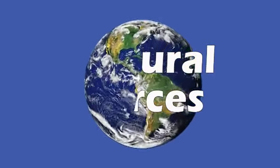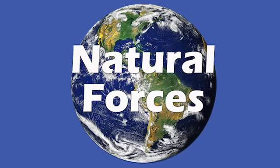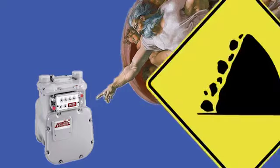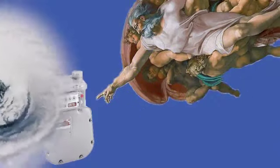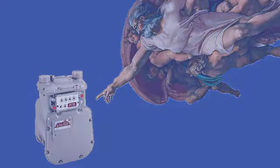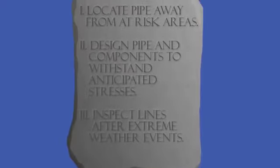Next comes natural forces. You might think of these as acts of God. Things like landslides, subsidence, lightning, or extreme weather events. So how do you prepare for an act of God? Just follow these 3 commandments. Locate pipe away from at-risk areas, design pipe and components to withstand anticipated stresses, and inspect lines after extreme weather events. We're getting close to the end now, so stick with me.